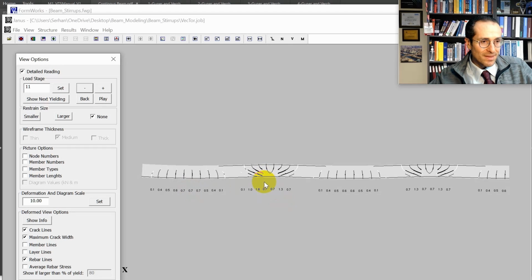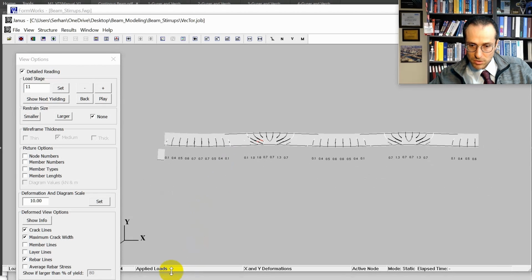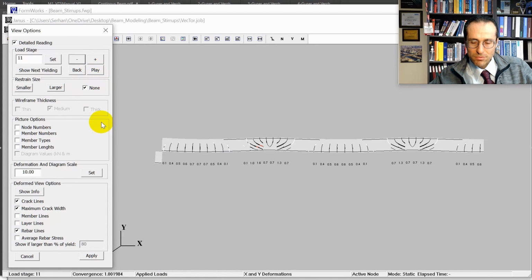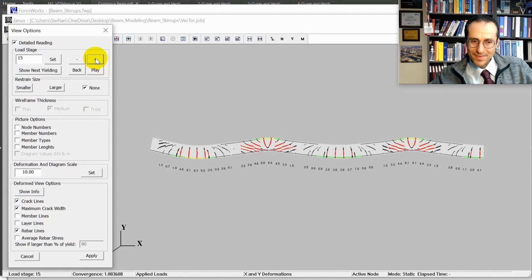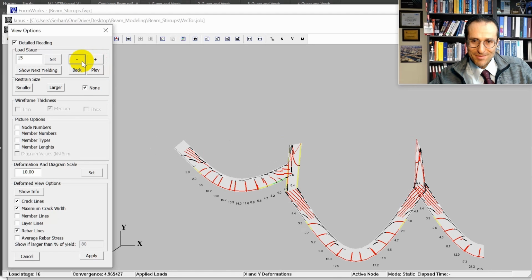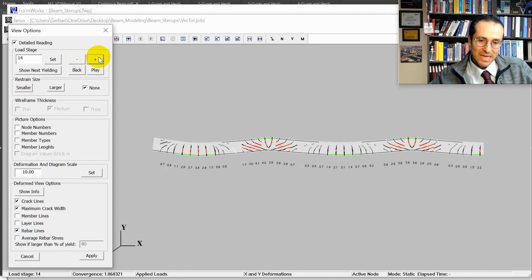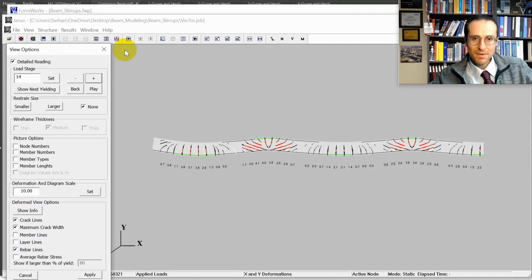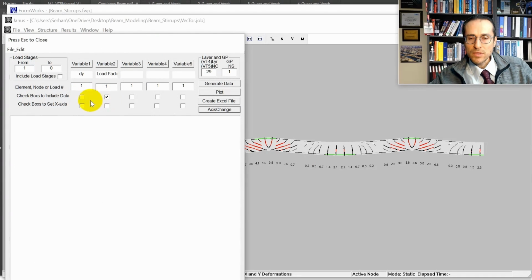No problem with the ultimate limit state. It is stable, it is safe. Convergence is pretty good, 1.002. Getting into trouble, definitely 13, even 14 would be the load stage to cut, but let's get the data. That's what we want. Include, it was node 48.